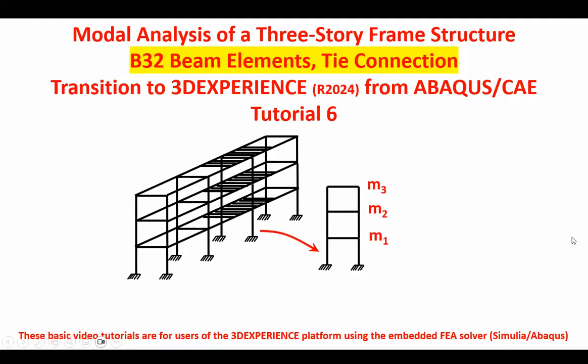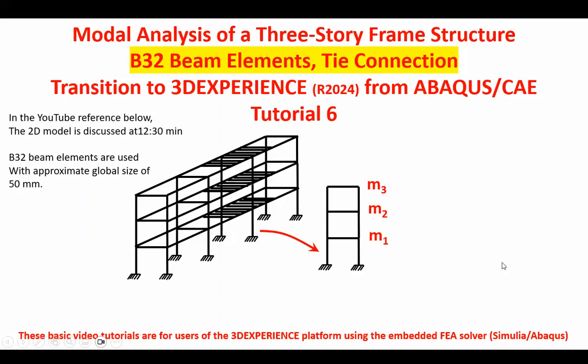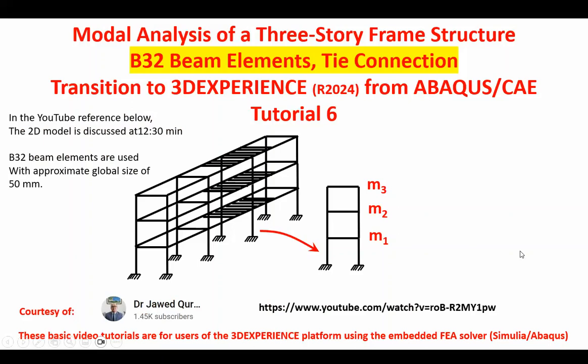The particular problem that I'm going to be doing is a three-story building. In reality, this is three-dimensional. However, if the frames are uniformly spaced, one can approximate that three-dimensional structure with basically a two-dimensional problem with multiple degrees of freedom. It is coming from the reference below, where this problem is done in Abaqus CAE, but its two-dimensional treatment, which I'm doing here, starts at 12 minutes into the video presentation.